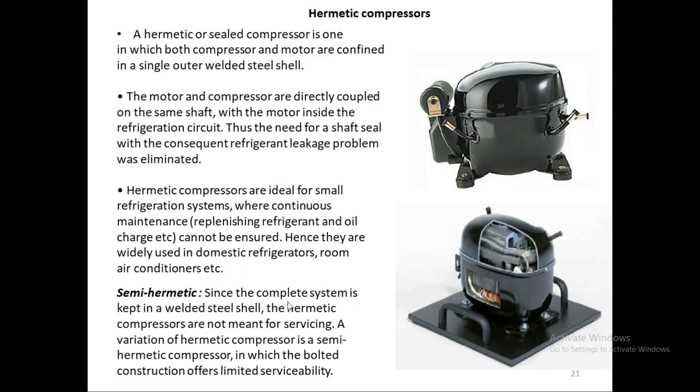Semi-hermetic: since the complete system is kept in a welded steel shell, the hermetic compressors are not meant for servicing. A variation of the hermetic compressor is a semi-hermetic compressor in which the bolted construction offers limited serviceability. So this one you cannot service because this is all sealed. This is welded together. The bottom part and the top part are welded together. So it cannot be serviced.